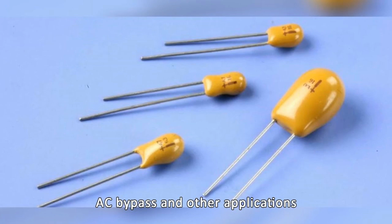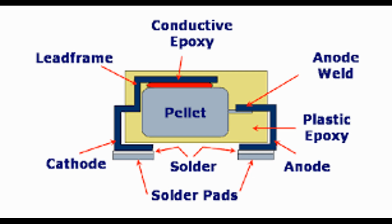Dielectric. The tantalum anode is oxidized to create a thin layer of tantalum pentoxide, Ta₂O₅, which serves as the dielectric material. This dielectric layer is extremely thin but has a high dielectric constant, enabling it to store a large amount of energy. Cathode, negative terminal. The cathode is usually made from manganese dioxide, MnO₂, or a conductive polymer, both of which are applied to the surface of the dielectric. This material allows the flow of electrons when the capacitor discharges.